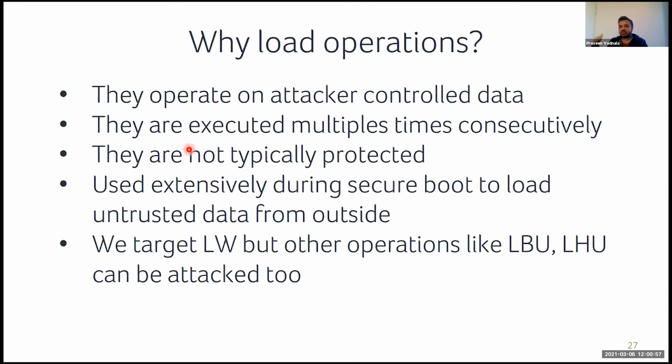And typically they are executed multiple times, right? So basically loading from memory, external memory to, for example, internal memory, there will be a bunch of load operations, loads and stores. That means these are executed a number of times during the copy. Of course, there are other ways. For example, if you use DMA, this is different, but in most of the cases earlier during your, for example, secure boot flow, you may not use DMA, you just do a simple copy.